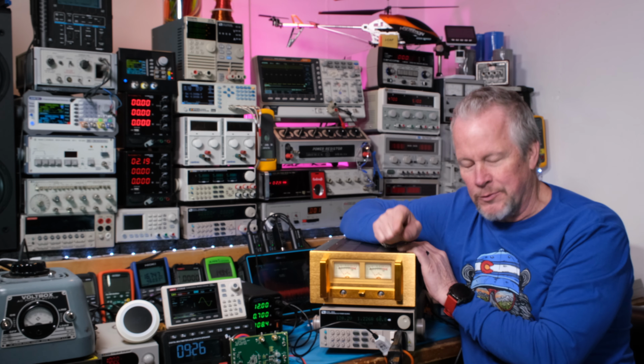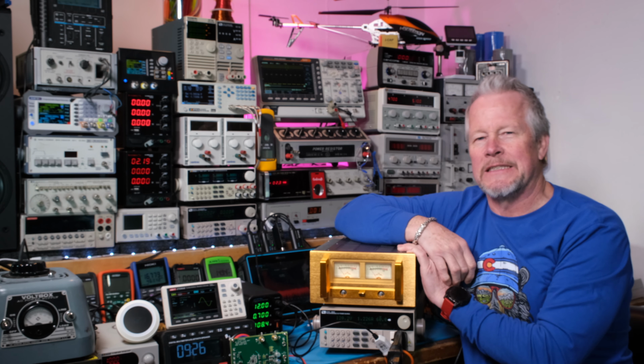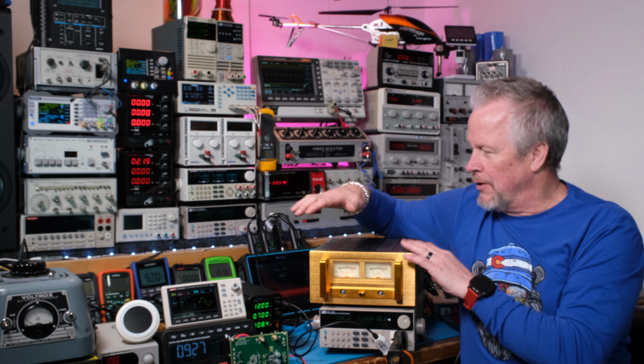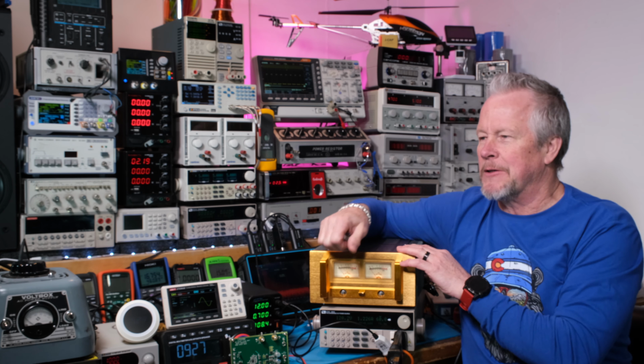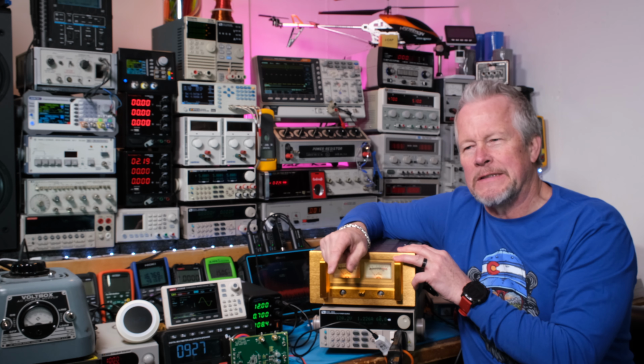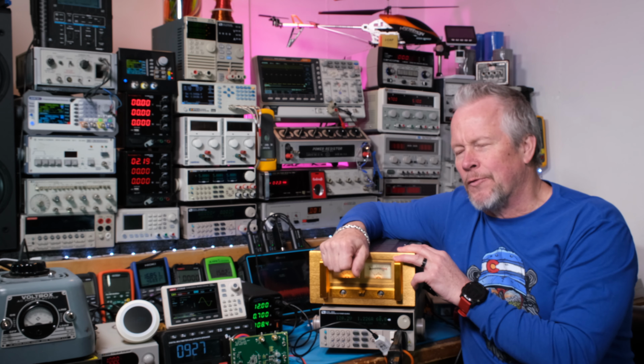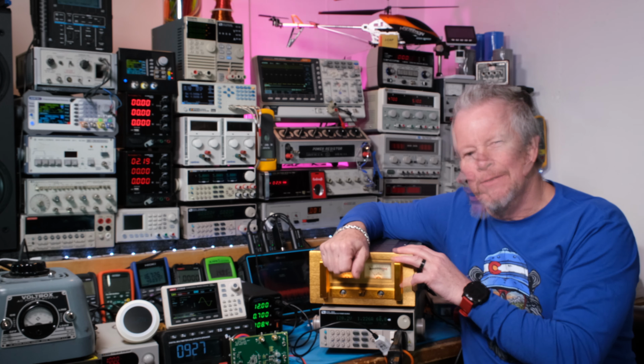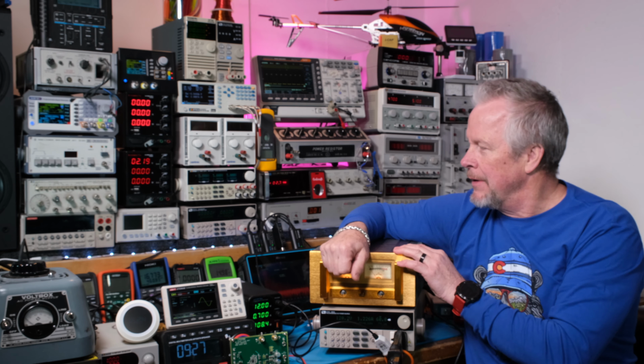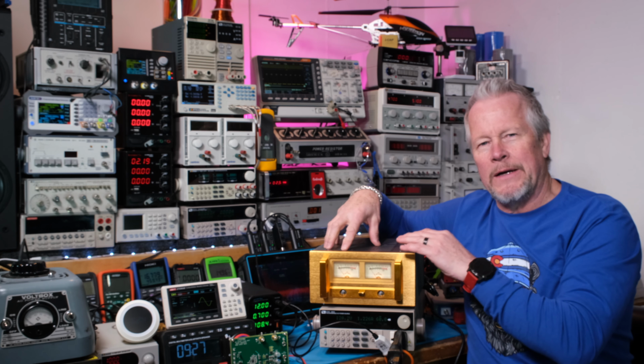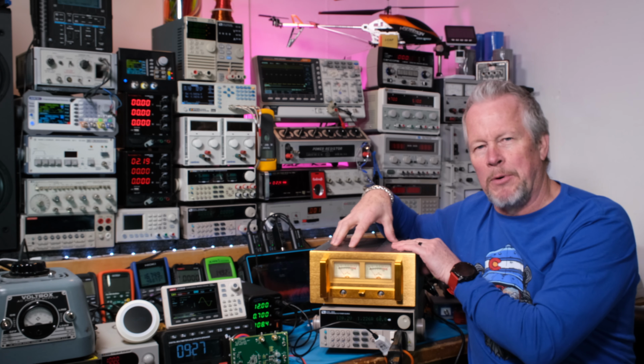But at 100 watts, we're seeing some pretty decent spikes. All right, so guys, a low frequency switching power supply is a little bit different than a high frequency switching power supply. In a low frequency switching power supply, you're going to take this 60 hertz signal, convert it to 120 hertz, and charge up some bulk capacitors.